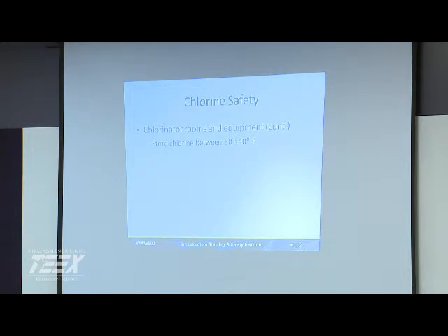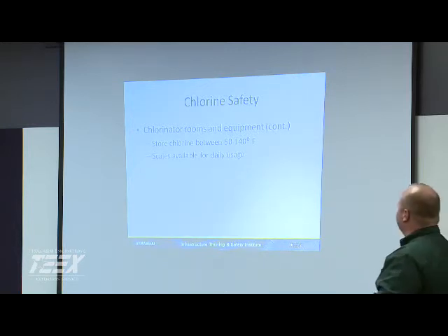Chlorine, I don't know if y'all have heated rooms. Do you have heat trace? We put a heater in there. We did have one that was overhead, but it just wasn't working accurately, so we just put in a little space heater. The room's small enough that it works. Temperature's real important. If you get it too low, you're not going to feed. I would imagine that'd be the bigger problem here. In Texas, we don't have a whole lot of problems, especially down south. It's hot enough most of the time that you want AC in there.